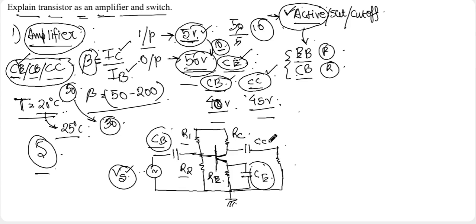And this is the coupling capacitor. This will couple the output to the load resistance. Okay. And across this load resistance, we will measure the V output or the output voltage. And one thing we need to make sure is that here we will apply our supply voltage, which is VCC, which can be taken as 15 volt. Okay. So here the current will be flowing as IE.